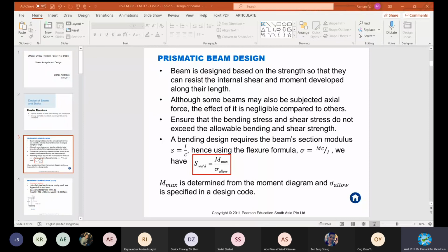That's what we did in the beginning of the class, like 2-3 classes before, when we found the strain due to pins and links and so on. Especially, the required spacing of nails or bolts of a particular size is determined from the allowable shear flow, which is equal to VQ over I, calculated at points on the cross section where the fasteners are located.